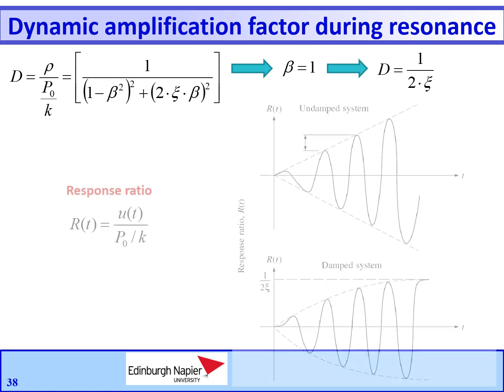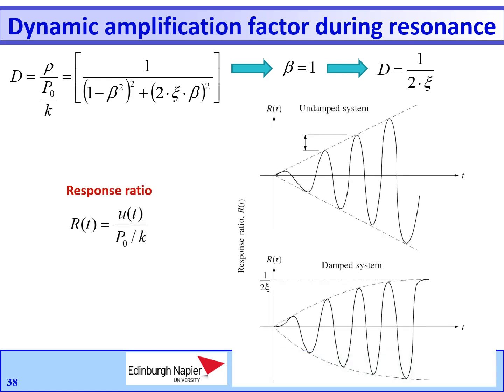So for omega equals omega n, the natural frequency, the deformation response factor is dimensionless and defines the amplitude that is followed by the displacement as a response quantity. The response ratio is plotted here for damped and undamped systems, and that shows that damping lowers each peak and limits the response to a bounded value.